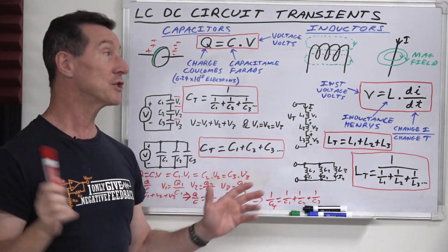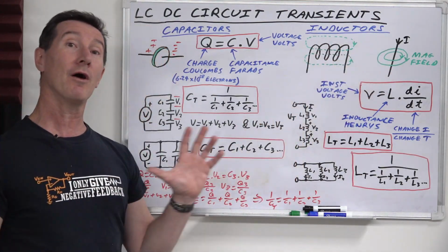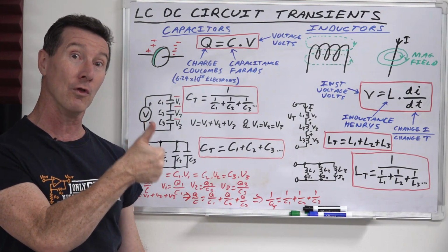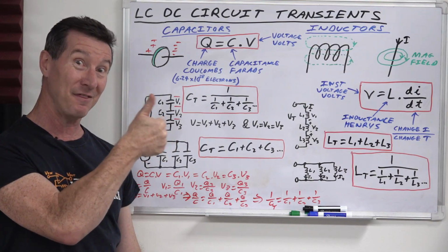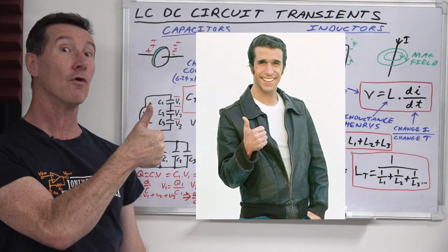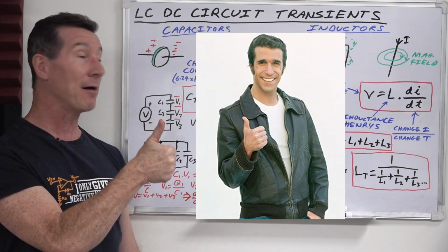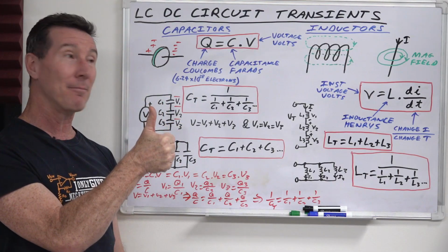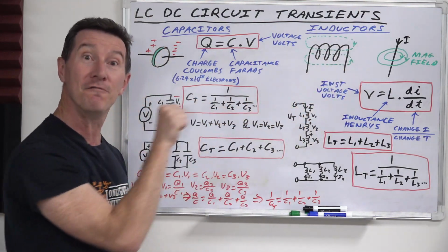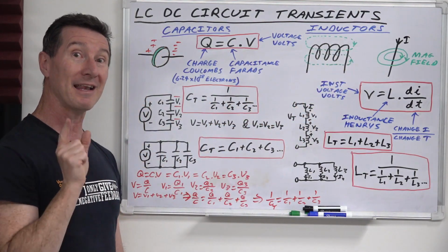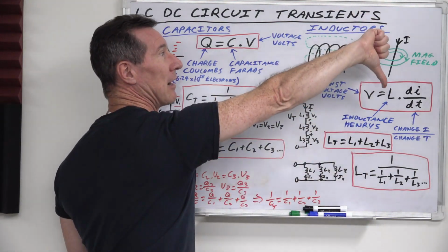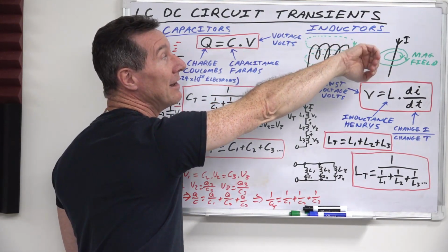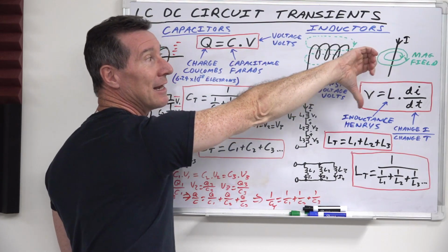And you might ask, which direction is the magnetic field flowing? Well, there's a handy little rule which you should remember, called the right-hand rule. Take your right hand like this, point your thumb in the direction of the conventional current flow, none of that electron current flow rubbish, conventional current flow like that, and your fingers like this will point in the direction of the magnetic field.